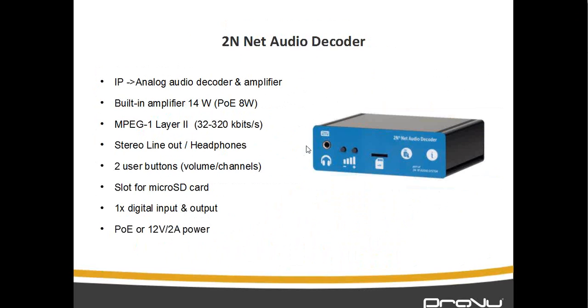There's a digital output and input as well, so you can connect an amplifier or a speaker to it. There is a built-in relay. I'm sure some of you are aware that the legacy system has some sort of relay to set the priority. If you want to trigger something to play, or play a certain recording when a certain event happens, you have a dry contact relay which can be triggered to play certain things.